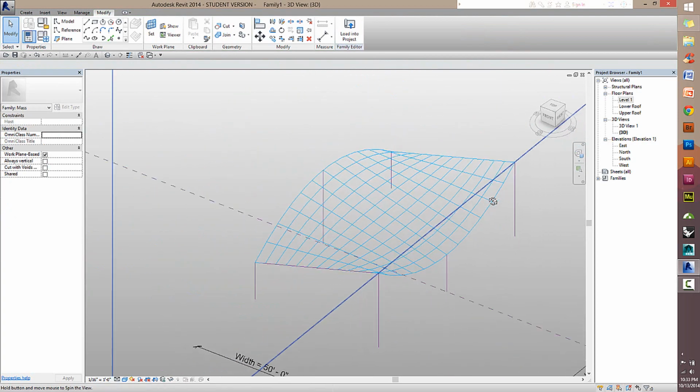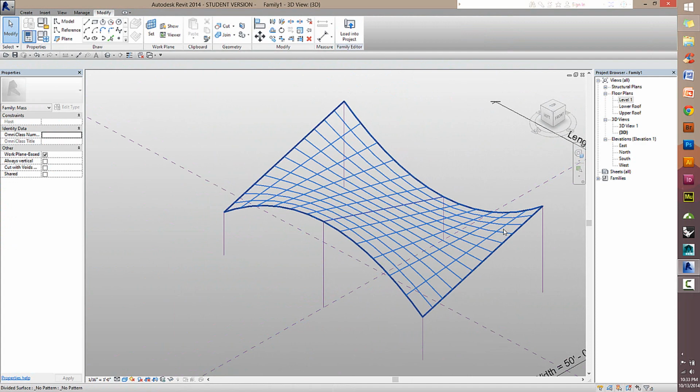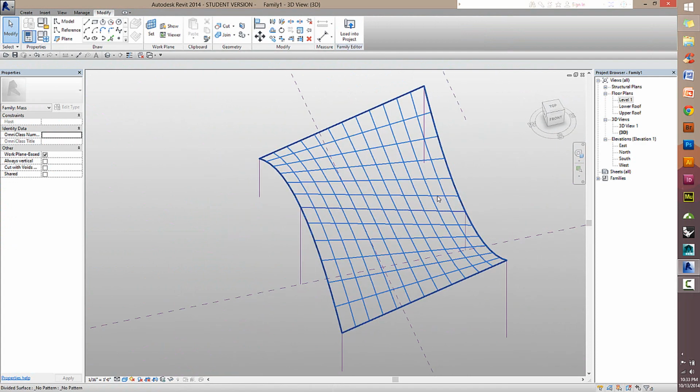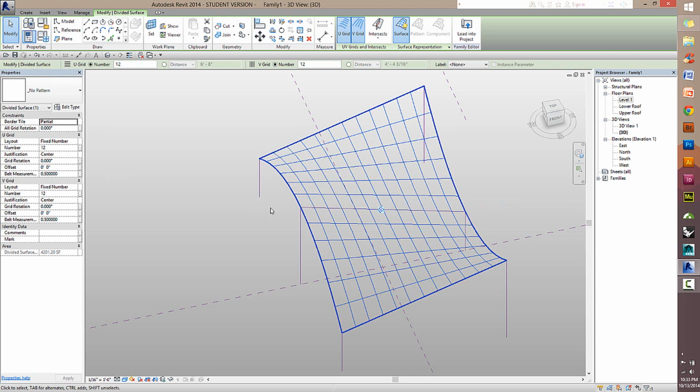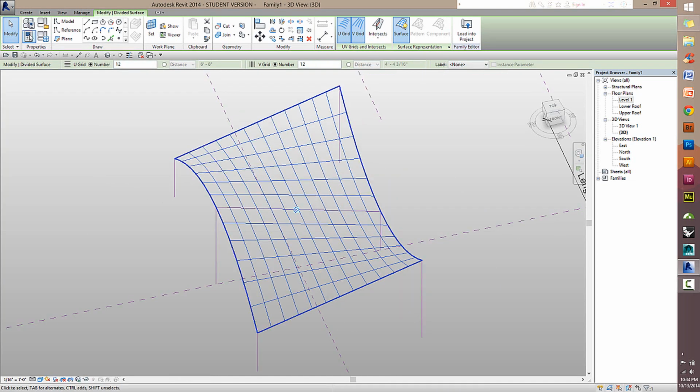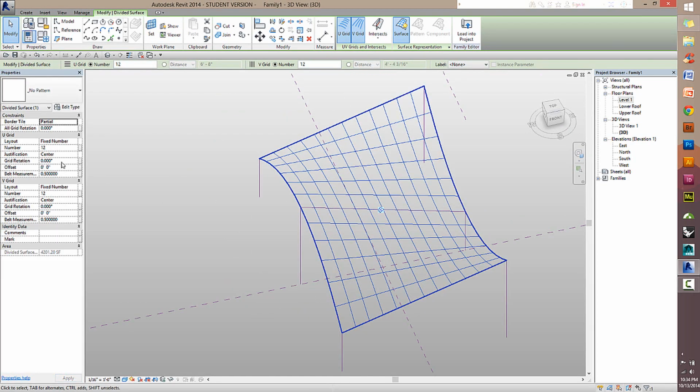You'll see that it instantly turns this surface into something that resembles a polygon mesh. It's not. It's actually a UV surface, much like any of the solid modeling tools in Rhino. And its UV grid is based on numbers that are given to it from this interface under the properties. If you ever accidentally close this, it can be re-accessed by this button right here.